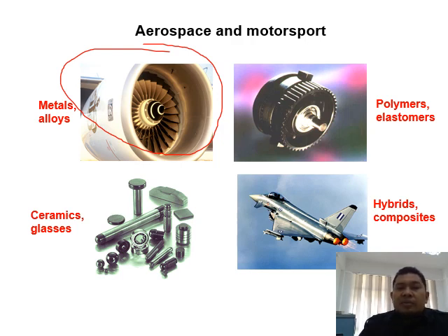And then, for example, the nozzle of the jet and the blade of the jet engine. Over here, you need to use very specific material. For example, for the blade, we probably use nickel alloys, super nickel alloy, so that you can have very high hardness, and of course higher tensile properties, talking about gigapascal level and so on, and then high thermal resistance, for example, temperature above 1200 degrees Celsius.